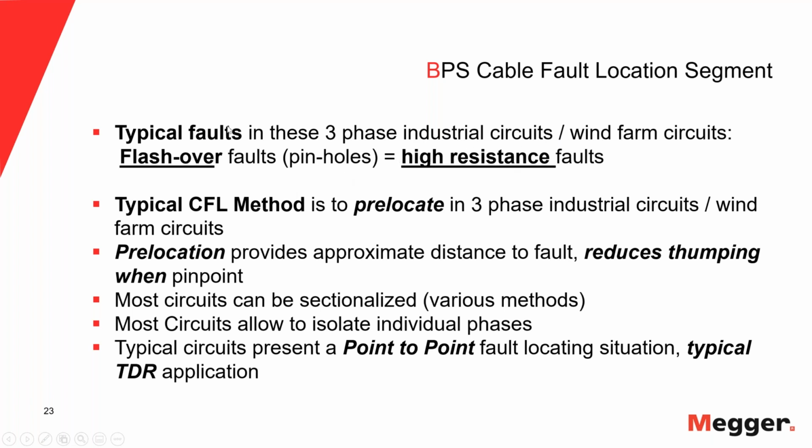Okay, and the most common fault locating method today is prelocation, that we do a prelocation in these circuits. And why do we do a prelocation? Because the prelocation gets us an approximate distance to the fault, and what it really does, it reduces the thump time that we need when we have to pinpoint. Typically, once you have a distance from prelocation, the pinpointing shouldn't take much more than maybe a few minutes to really narrow it down to an area of about a square foot or maybe 2 square feet.